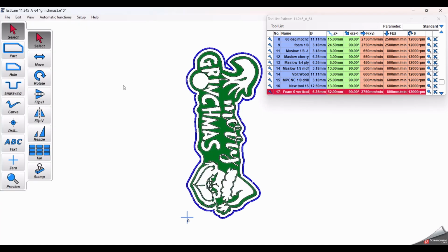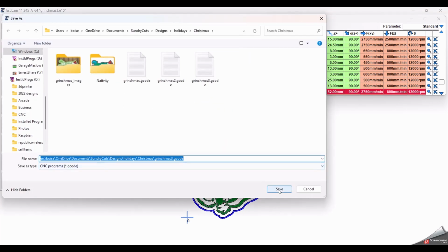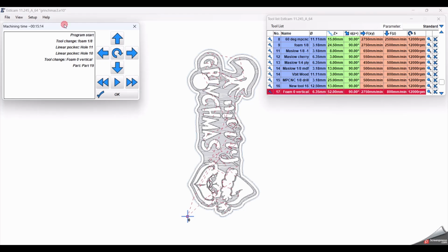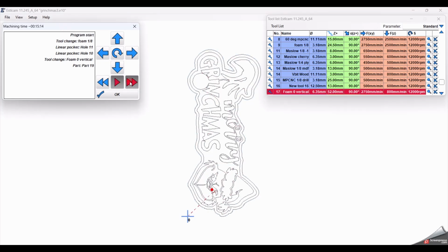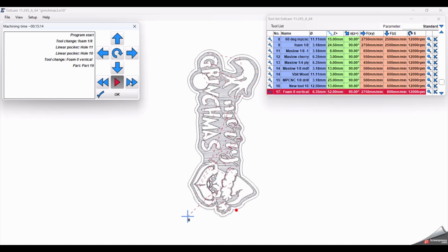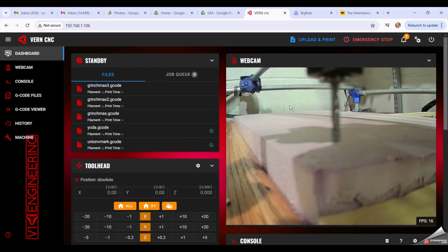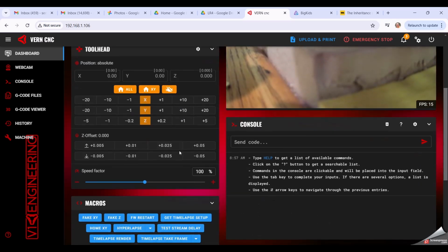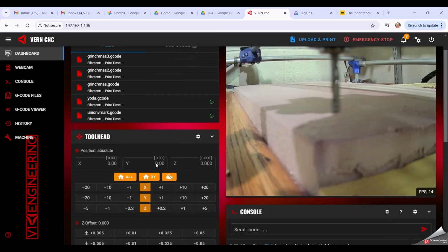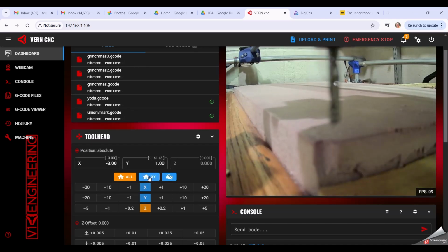And then say OK. It will generate your G code. You then save it. You can look at how it's going to cut, the order that it's going to go, if you want. That's the preview. And then you just hit OK when you're done. You can go back to your G code file section. Or you can, in Clipper, home the X and the Y. Then it turns on the X motor, then it turns on the Y motor, and it's ready to go.